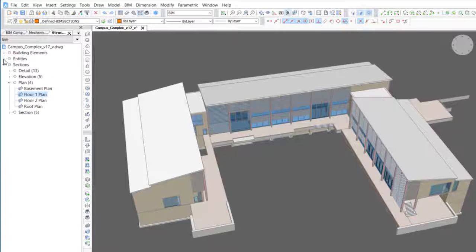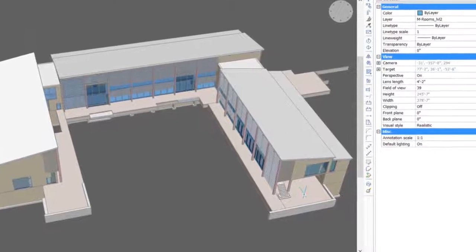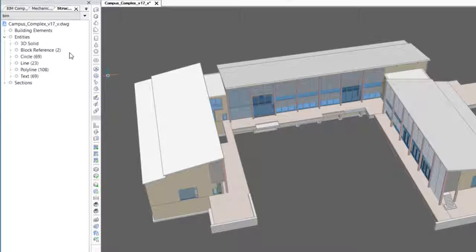If you recall, we mentioned that all entities within a BIM are included in one of the 3 categories. So, if we go to Entities and there are 3D solids included, it means that there are some solids that haven't been classified or had compositions assigned to them. Depending on the stage of the project, we can handle this differently. If we're at an early stage and we haven't defined the slab compositions yet, we can select it. Select Composition Slab from the quad. Now it is classified as a slab.